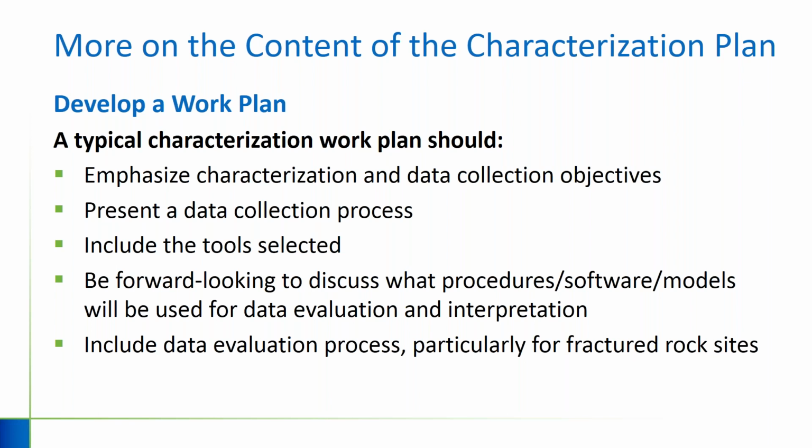How you're going to handle the data, and that's especially relevant for fractured rock sites, because you may be doing some geophysical logging, maybe some televiewer logging, and you're generating the kinds of data that maybe you're not used to managing if your only experiences with unconsolidated sites. So some of that can require specialized tools to be able to handle and visualize all those kinds of data. So you don't want to wait until you already have the data to realize that you don't know how to handle it. You want to look at that at the work plan stage. Then you want to talk about how you're going to evaluate the data.